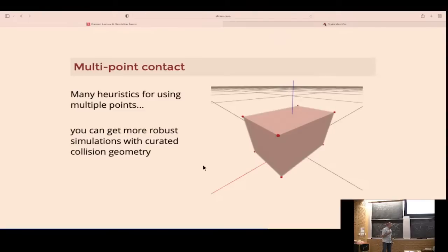Why? I'm telling the simulator, do your best in all these hard places to pick one point to summarize the force, but go ahead and put an extra point at the corners. Always do that. We get one contact force per collision geometry pair. So by having extra points declared to the side, I'm just saying always pick the corners and then do your best on the interior.